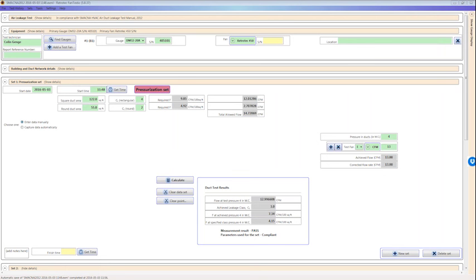What they did is they went in there and measured the duct leakage, and they found it was roughly, I think, 10 or 15 times larger than it should have been if it had passed code. They used the Aeroseal system to seal the duct, and I think they got like a 93% reduction on it. Joe's quite right.